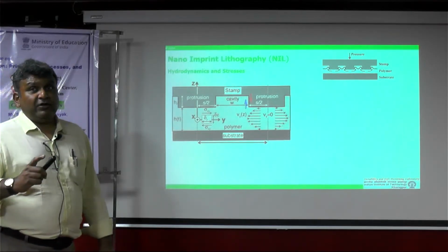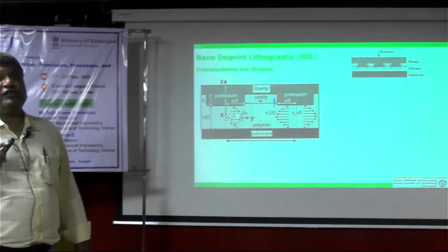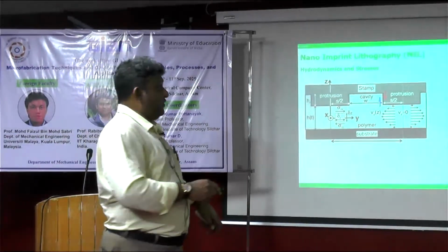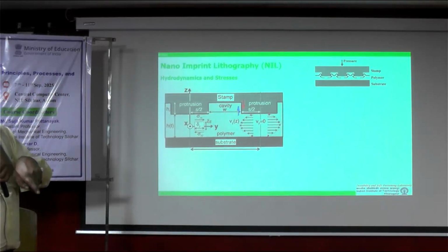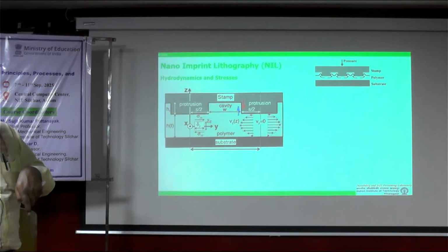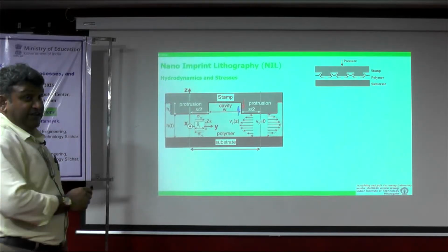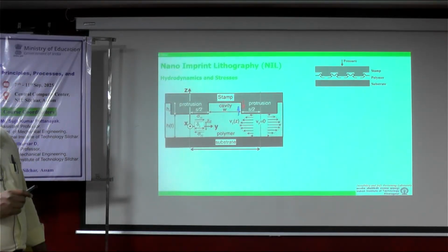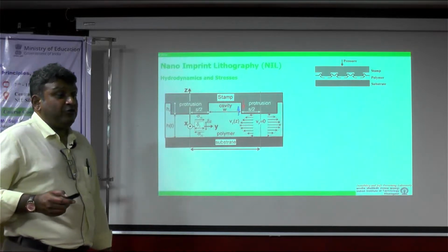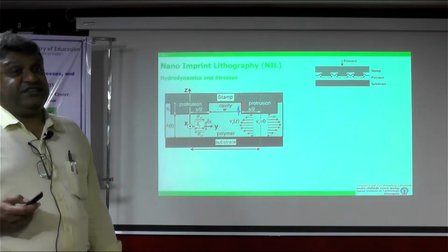And probably you have all heard in your fluid dynamics lessons about the no-slip boundary condition. So you see here, as the stamp is coming down, the liquid adjacent to that has a velocity downward, whereas at the central part, the liquid is rising. So the velocity gradient is actually very, very high. And what does velocity gradient lead to? Velocity gradient leads to enhanced shear stress.